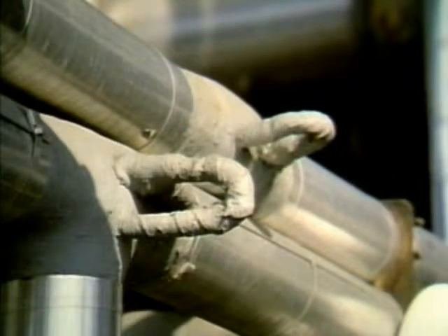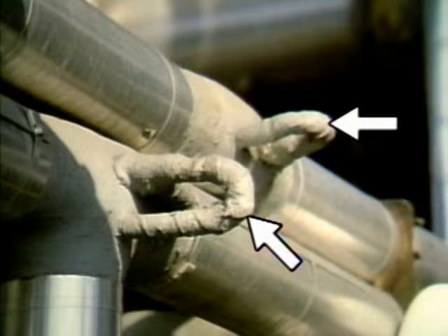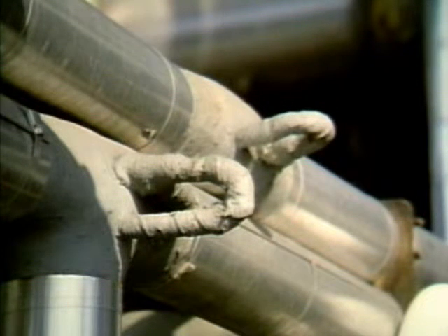The viscosity of a liquid can change with changes in temperature. For this reason, heat is often applied to fuel oil pipes in cold weather. Heat may be applied using electrical conductors under the insulation or small tubes that carry steam. Applying heat to piping this way is called heat tracing. Heating the fuel oil decreases its viscosity and allows it to flow more easily.